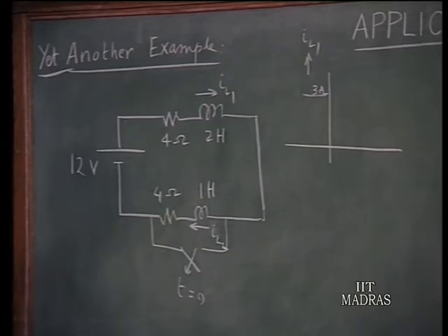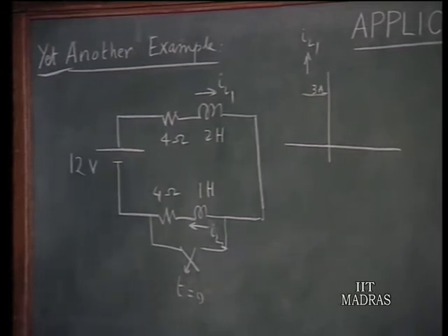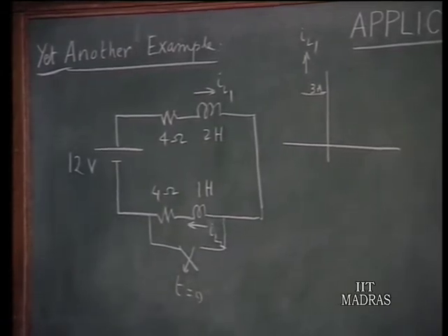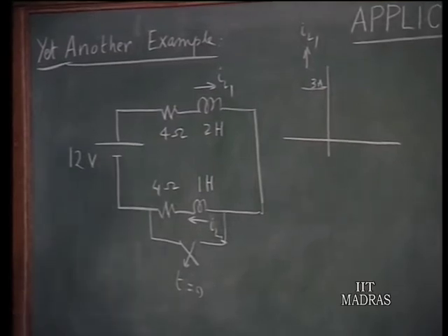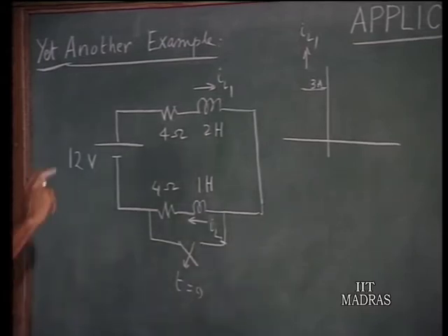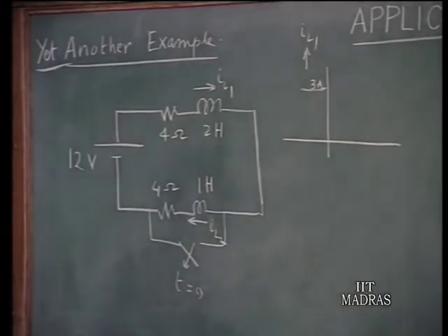In the case of differential equation approach, we have calculated the t equals 0 plus conditions separately. Now, let us use the Laplace transform method and show that once you substitute t equals 0 minus conditions, 0 plus conditions almost immediately follow in the normal routine. You do not have to make separate calculations. So, let us use 0 minus conditions and solve for this circuit.